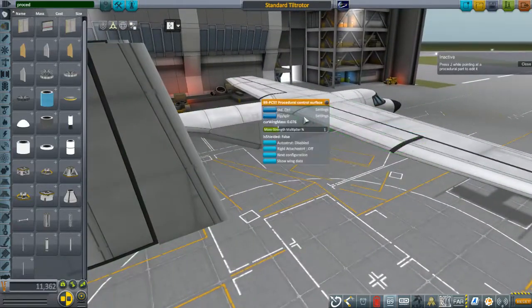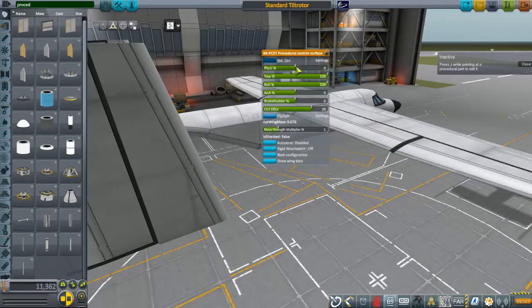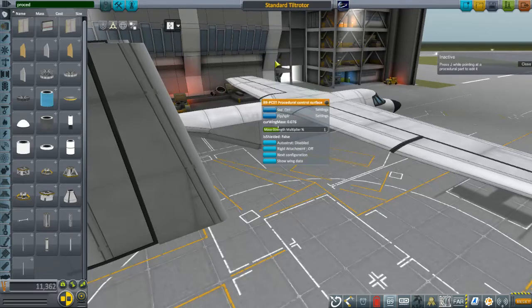We're going to start with the interior flaps. Standard control surface, I don't actually want these to act as flap surfaces. I want these to act as deep sweep spoilers. And that actually requires me to... Spoilers usually kick up. I want them to kick down, specifically because these are going to be used in 45-degree engine flight as a drag modifier.